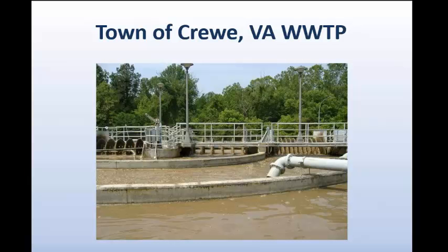That lowers the surface agitation, and so that lowers the dissolved oxygen levels. The discs provide not only oxygenation, but they also provide mixing. So when we removed the disc, the DO was in fact lowered, but it began promoting settling, and it lowered the mixing. And when we're dealing with a suspended growth process, activated sludge, mixing is what brings the pollutants into contact with the microorganisms, which remove them. So that wasn't going to work for us because the mixing energy was lessened, so the mixing was lessened, so the removal efficiency was lessened.